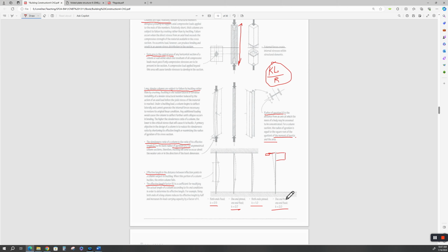That's why you see these big light poles or traffic light poles that have the cantilever arms out, those big arms out, and they got all those traffic lights hanging on them. Next time you're at an intersection, look at the base and see how they handle the base. Because what this is going to want to do, that's pushing down, and so that's when I want to bend it over in this direction.